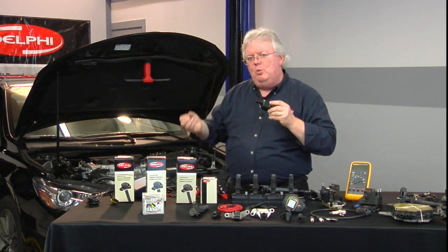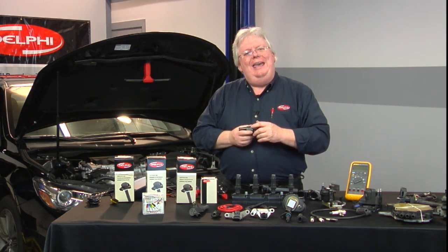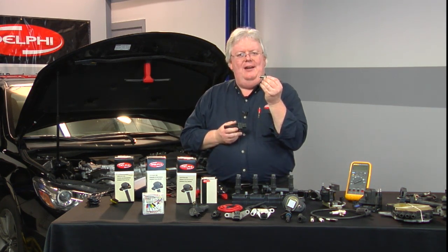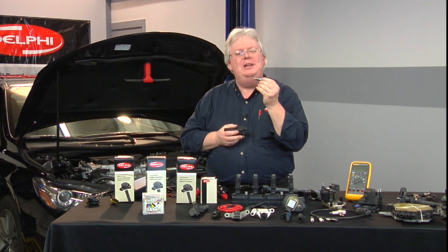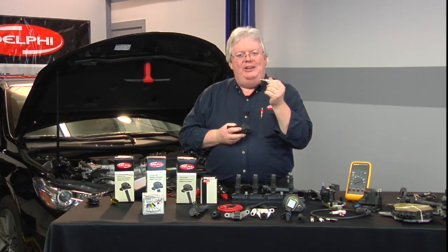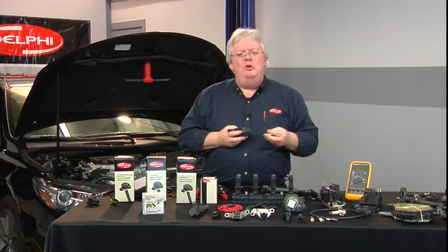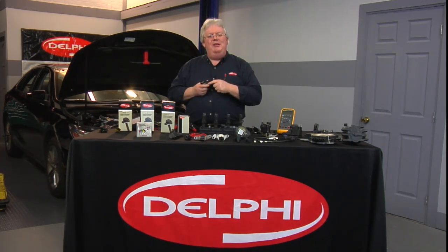Now you fix that plug wire or that worn out spark plug, and now it runs okay at idle and light throttle, but when you have tons of air packed into that cylinder's air gap in that spark plug under heavy load, that's when the voltage demand is so great, the electrons taking the path of least resistance say, you know what, why don't we go jump across that little scar tissue, that little carbon trace that was burnt internally between primary and secondary windings.